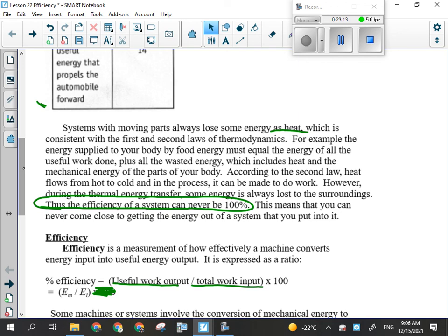the flows are variable. I don't know if you've ever seen this in the Bow, but the Bow has several dams on it, and some times the Bow is a raging torrent, and then the next day, you can walk across it and not get your chest wet. It just depends on how much they're holding back and how much power they're generating, and that's true anywhere. Anywhere where there's a hydroelectric dam, the tailwater after the dam is going to be variable, and that can have detrimental effects on fish species that are native to that area. So that's the drawback to a hydroelectric dam: the way it changes the flow of a river, and the way that it affects the fish species and the other aquatic species that are there can all be greatly affected by that.